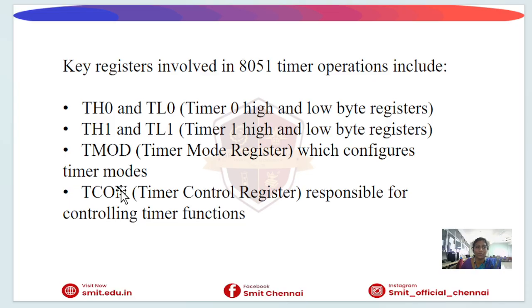Regarding the timer registers, TH0 and TL0 hold the high and low bytes of Timer 0, and TH1 and TL1 hold the high and low bytes of Timer 1. TMOD configures the timer mode and operation, and TCON controls the timer start and stop operation and indicates the overflow.